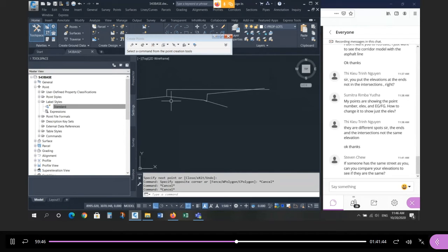I'm using AutoCAD to demonstrate what I'm saying. I'll show you how to do it in a moment. But do you understand why we're going to use the existing centerline elevation, add 0.3 vertically, and then use that on the street line? Because that will be compatible to a future boulevard elevation. Now, is it going to be exact? No, but it'll be close.